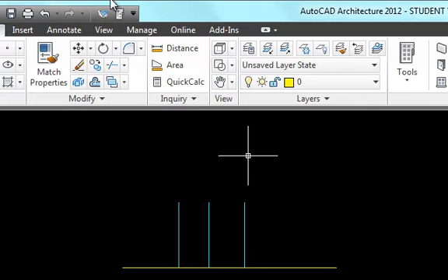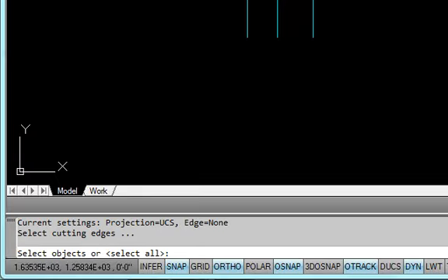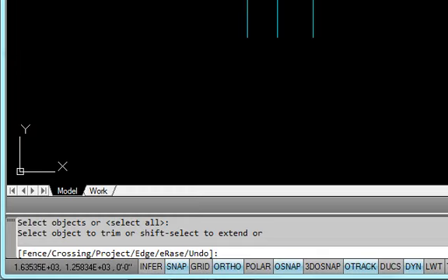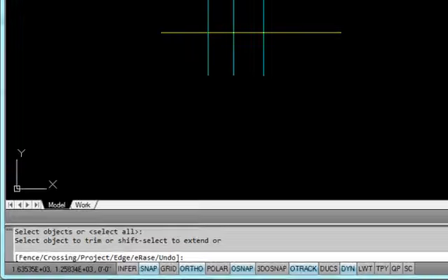Let's use the Undo command. Let's type in TR Enter. Notice in the pointed alligator brackets at the command line, Select All is the default, which means if we push the Enter command one more time, everything on the screen is a cutting plane.